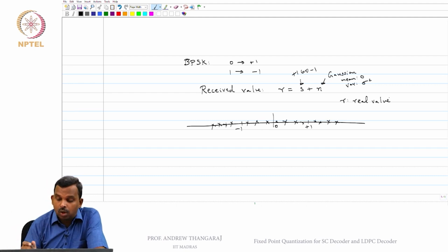However, in implementations, when you want to put your decoder on a chip or on a processor on a board which has low power, typically people don't use such very high levels of quantization. You can't use 64 bits per received value, and all that is really hard. In fact, the number of bits they will allow depends on the area that you can have on the chip, etc., maybe just 5 bits or 4 bits per value. So this is theoretically infinite precision.